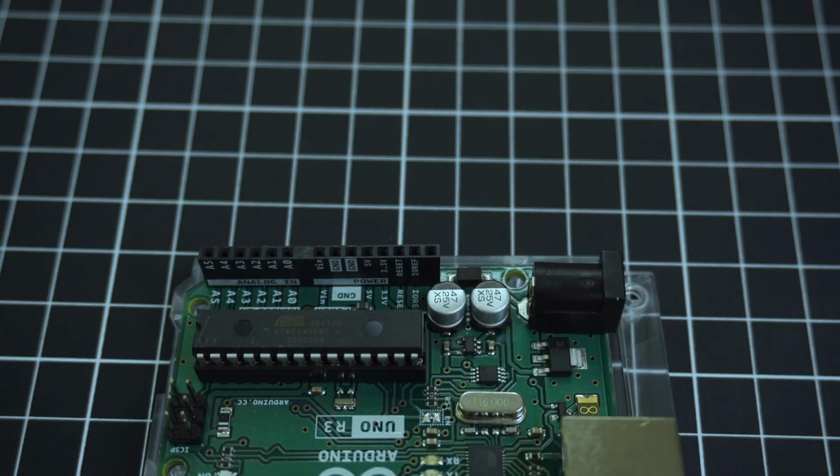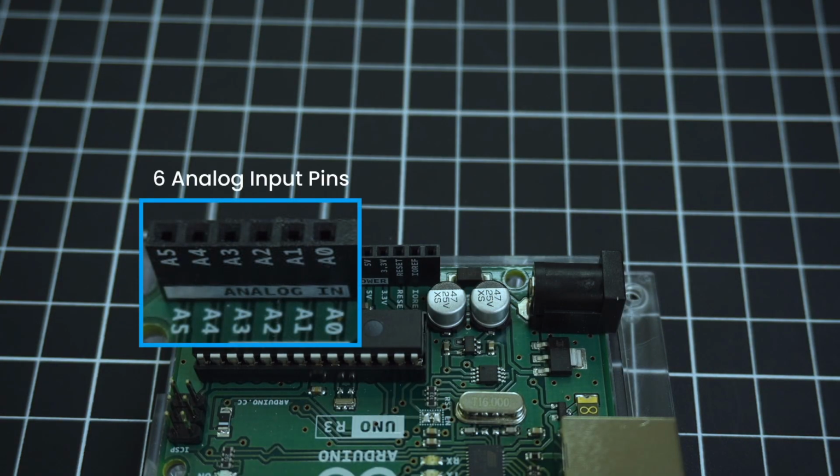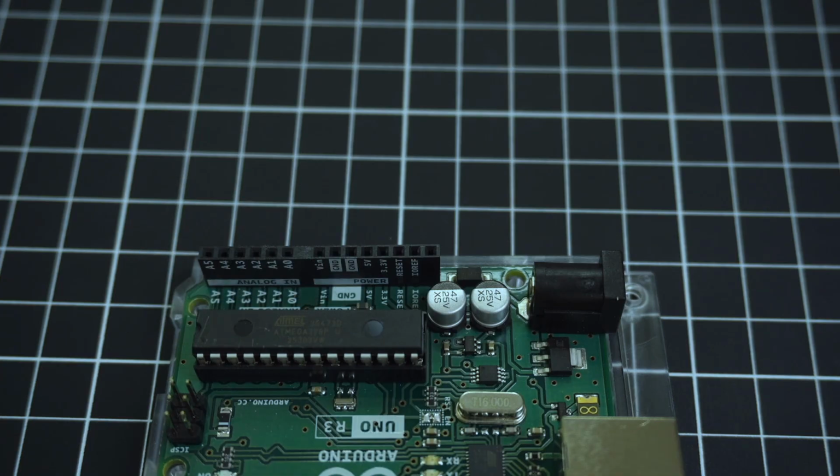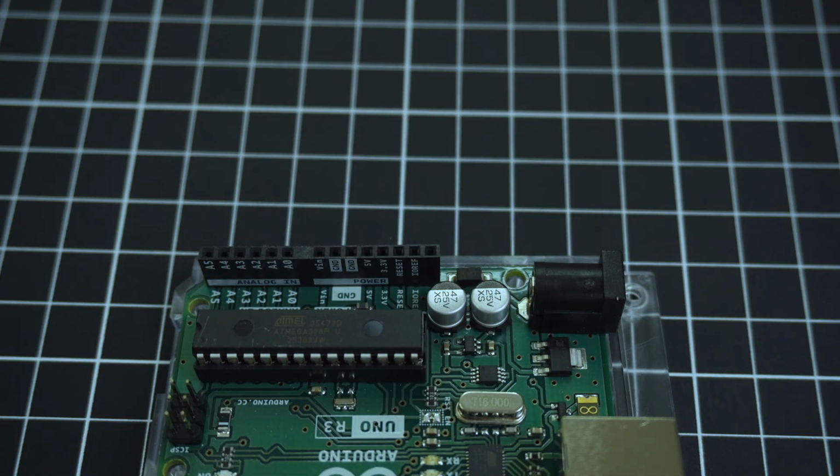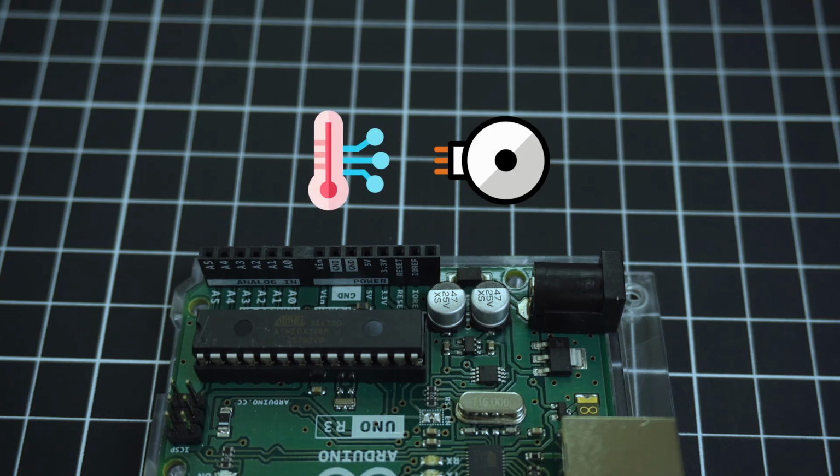On the opposite side of the board, there are 6 analog input pins labeled A0 to A5. These pins are used to read analog signals from sensors. For example, you can connect a temperature sensor or a potentiometer and measure varying voltage levels.